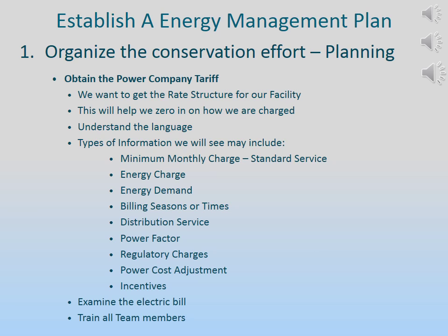Take a look at the determination of billing demand and read it. We read that the kilowatt demand is a 15-minute integrated demand. So for example, when we turn a pump on, let us say it's a 15 horsepower pump, then we are drawing approximately 15 kilowatts. Your electric meter that is reading that 15 kilowatts has a ratcheting feature. That means that if we left it on for 15 minutes, it locks at 15 kilowatts. If we shut it off somewhere in between, wherever the ratchet was, it's where it stops.